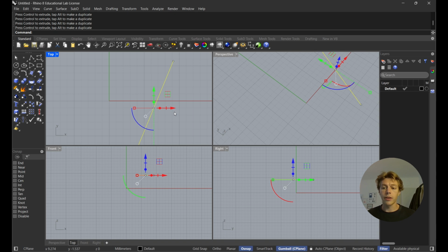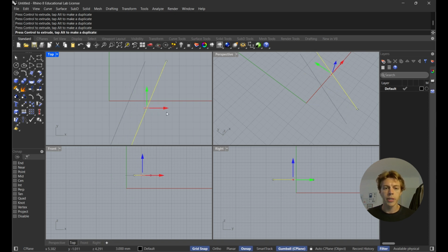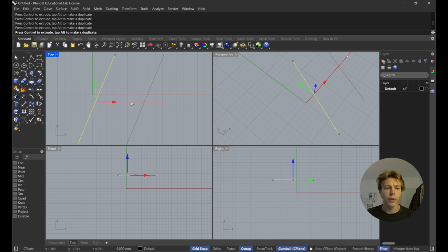I can turn on this other option called Grid Snap, which will do little intervals of the units that we are having in this file. For example, my file, if I look down here, is in millimeters. So it's now jumping 1 millimeter every time. That is already better. But because I drew it without the grid snap, this will never fit into anything.